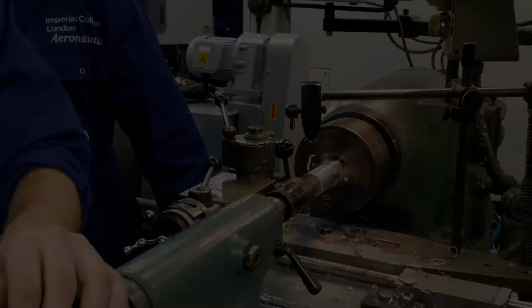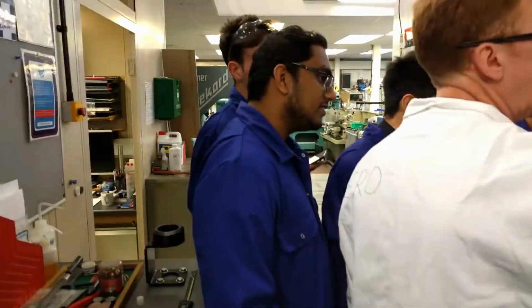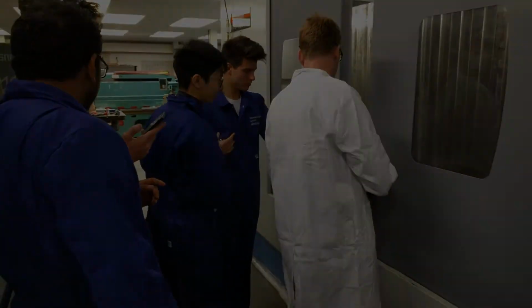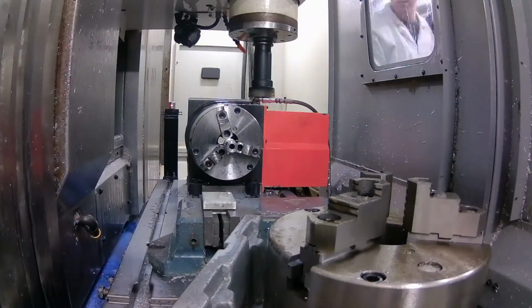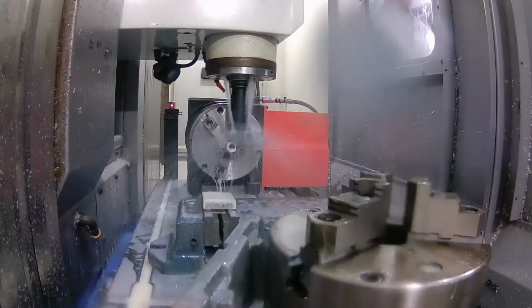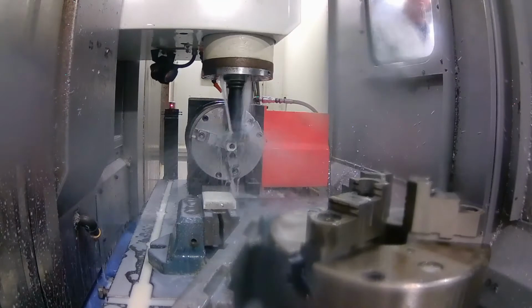The partially shaped aluminium hub was then placed in a CNC machine and precisely cut into an octagonal shape according to our CAD file. Finally, a keyway slot was punched into the hub.